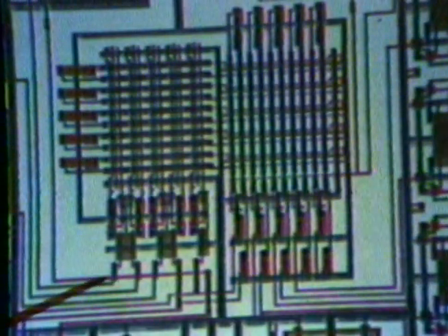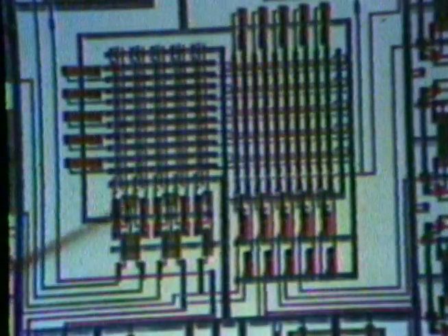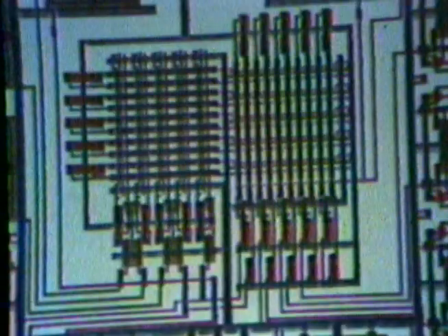The input gets first inverted with this. Well, you can't see it very well, but it's just double inverters driving the vertical red lines here. And on the outputs, we have the phase 2 clock line coming in here, and then 5 pairs of inverters to half register those outputs. 2 of these bits are fed back in, just as in that previous drawing, into 2 input bits.